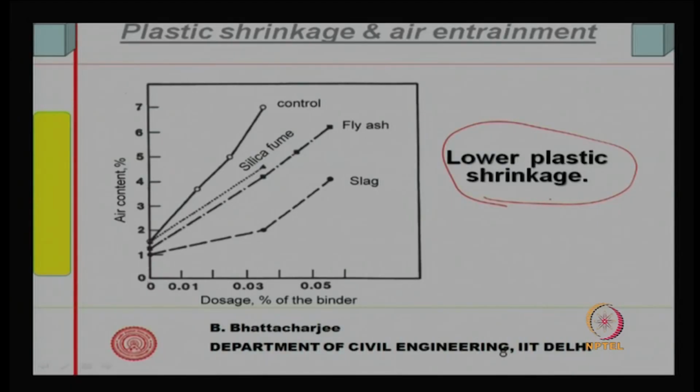Now, air entrainment is done in order to improve the frost resistance, where freezing and thawing is a problem, for example, in cold climates. So, you would like to have higher air entrainment, and we generally add air entraining agent, which I have mentioned earlier, that actually changes the surface tension of the water in the paste, and thereby makes it easy for bubbles to form.